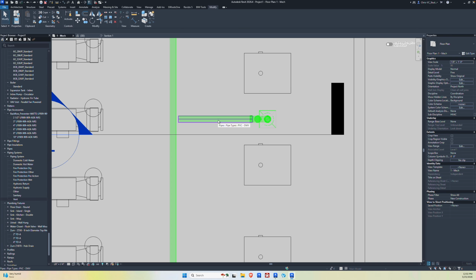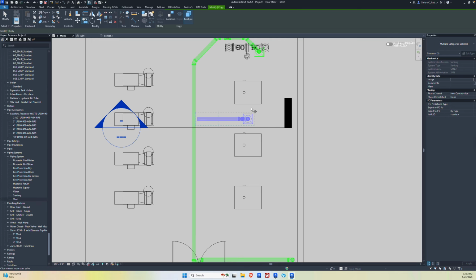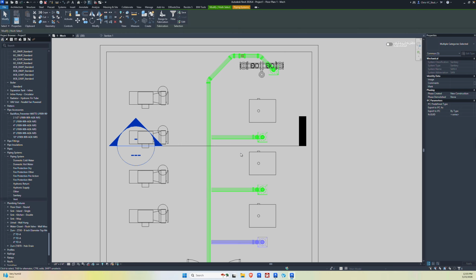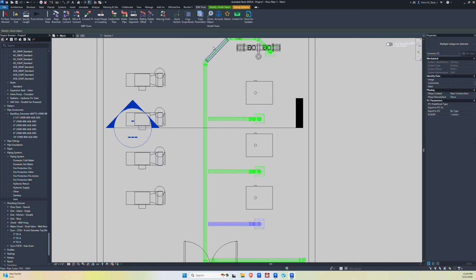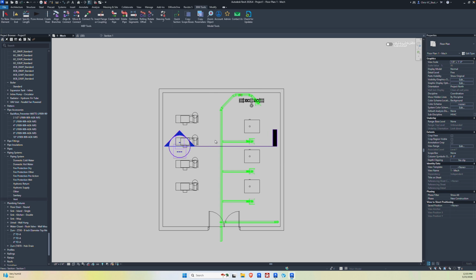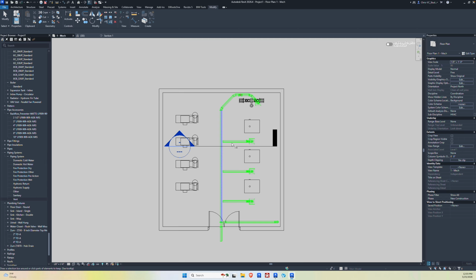So what we'll do is we just don't want one. We want multiples. So let's go ahead and copy this. And now we'll come in here. We'll go to BIM Tools. We'll go to Align Branches, click the main, click the branch, click the main, click the branch, reoccurring theme. And then now we can use the Align tool, but we can multiple align elements. Boom, boom, boom, boom.